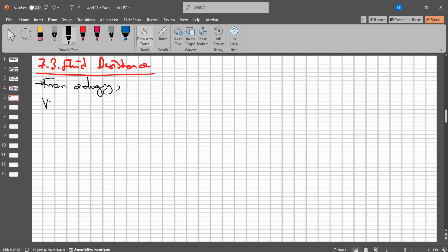So, from the analogy, we can write it. The voltage is equal to the I times R, right? What is the analogy of the voltage value in the hydraulic one? Yes. And so this is the R, and so this is the M dot, right? This is the analog with these denominations. And so, in the standard definition, we can write that the resistance value can be calculated with dP over dQm, or dP divided by dm dot.